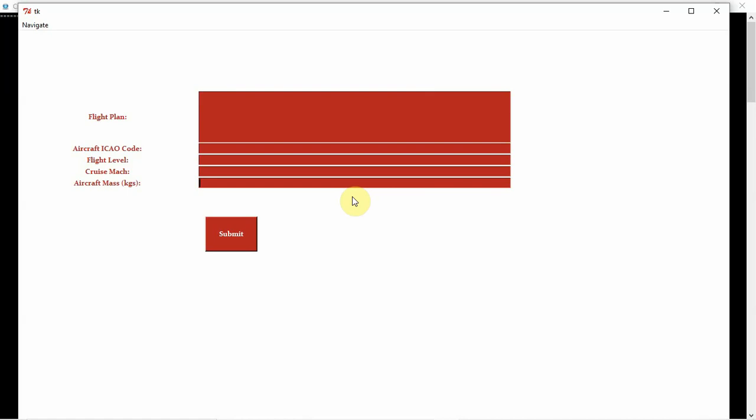The vertical profile is the file which will be generated, where it's a flight profile that corresponds to the altitude and speeds reached as a function of time and distance traveled. A profile follows a sequence during which the typical configuration of the airplane will evolve. The typical sequence of the flight envelope is takeoff, initial climb, cruise, descent, approach, and landing.